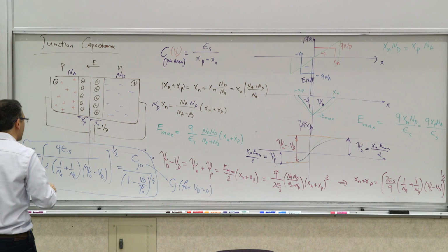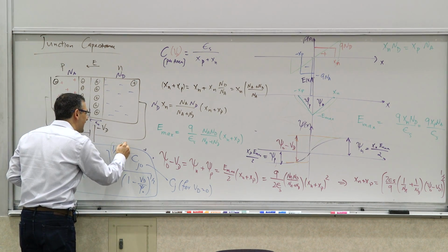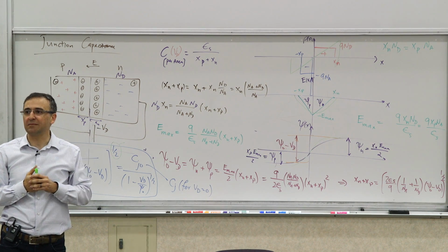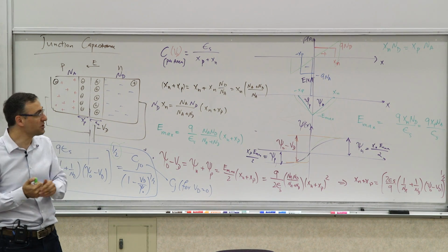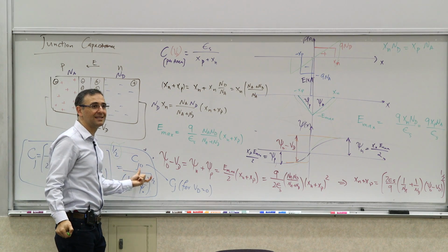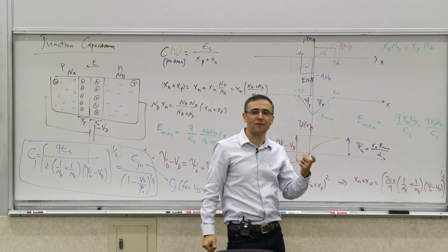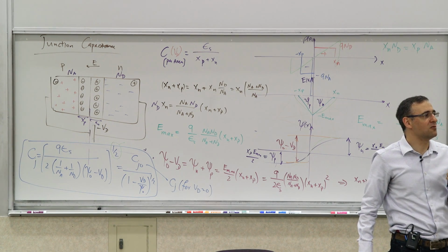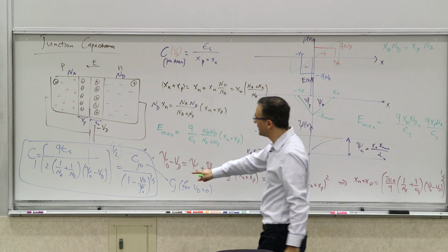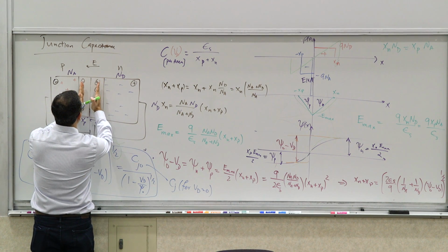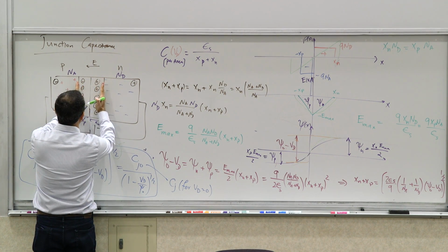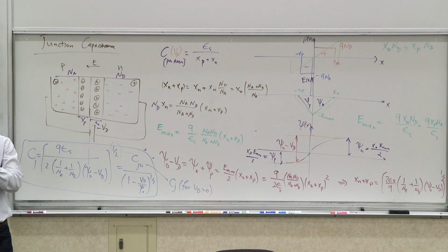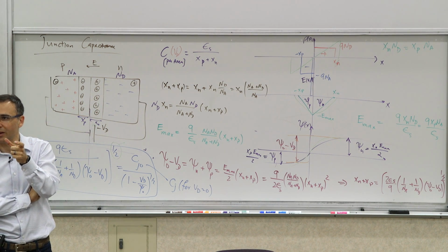So this exponent really tells you something about the profile of the junction. In fact, from that measurement, you can actually determine it. The measurement of this capacitance is the prominent way of determining or measuring the profile of a junction you've made. You measure it for different values of VD, which basically shows the profile at different distances, because they produce different junction widths.